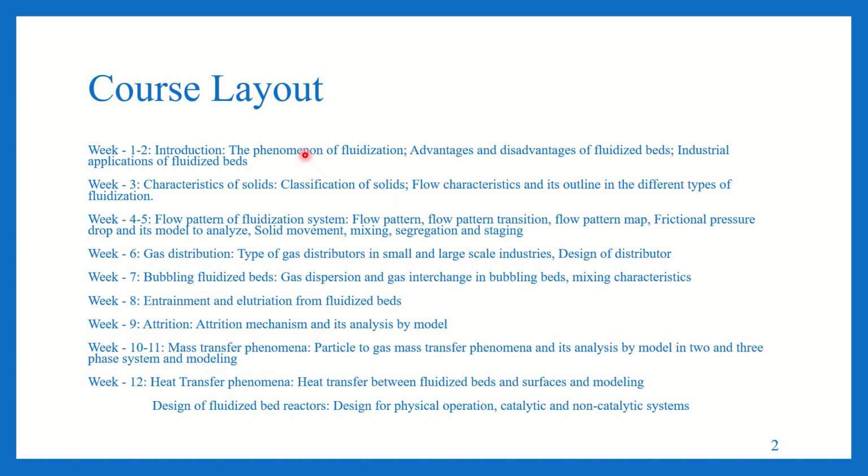We have seen what fluidization is. Fluidization is where we pass fluid through a packed bed at a sufficiently high velocity so that the particles start behaving like a fluid. The fluid-like behavior is imparted to the solids. This has various advantages, like uniform heat and mass transfer taking place inside the fluidized bed, which enhances it. Also, in the packed bed there are chances of hotspot formation, which is rectified here.